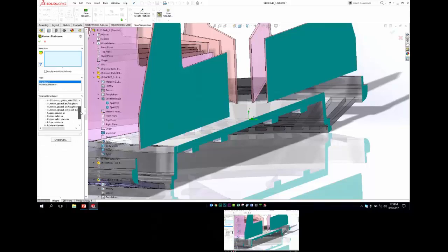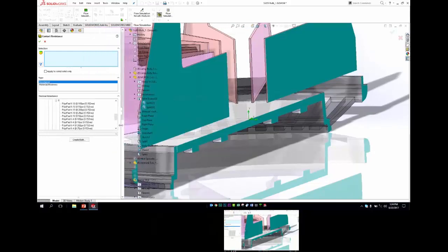It's resistance. Let me see if I can find an interface material. I kind of have to dig deep here to find it. It's Polypad K. So we're going to just choose one of these, a contact tape. This one, Polypad K at 25 PSI. So that's going to be how much pressure is applied when you actually bond that spreader plate to the aluminum or the copper part of the heatsink. Choose that surface.